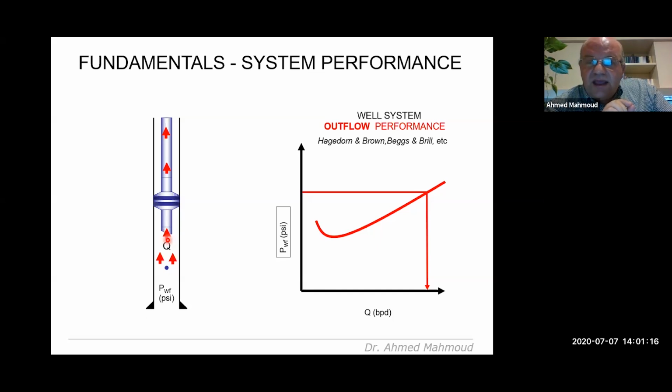entering the tubing. And this distance I have traveled from in front of the perforations up to the point of entry of the tubing is where we have a constant ID, which is the casing ID. And you are moving from this depth up to a higher depth. Typically, you will be losing pressure. So this is where you are in the beginning in front of the perforations, and as you move up, it goes down.